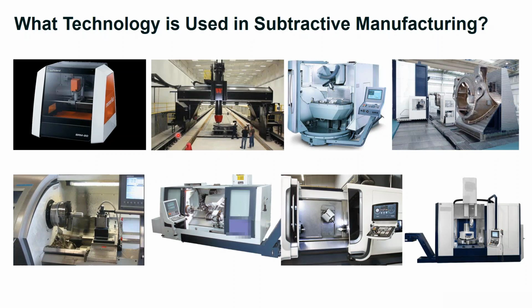The second machine here is a slightly bigger machine. It's about 100 meters in the y-axis direction, and this is also a 5-axis machine. It's a head-head machine because the rotational axes are in the head of the machine. The third machine is a more typical 5-axis machine used for the mold and die industry. And this is a head-table machine because we have 1 rotational axis in the head and 1 rotational axis in the table.